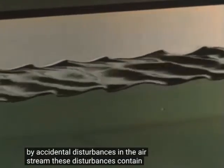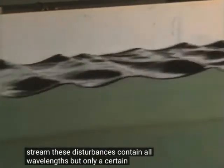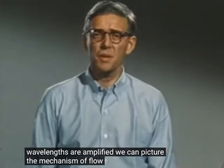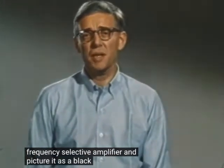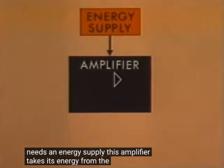These disturbances contain all wavelengths, but only a certain range of wavelengths are amplified. We can picture the mechanism of flow instability as a frequency-selective amplifier and picture it as a black box, although this is really oversimplified. An amplifier needs an energy supply. This amplifier takes its energy from the airstream.